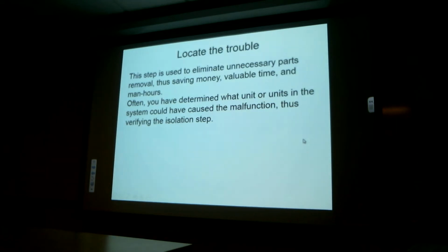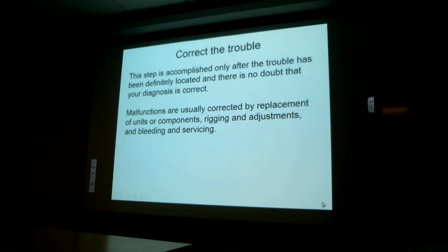The problem was that the vent opening at the fuel cap had been blocked by dirt. So I went out to the fuel tank, opened the tank up, and I heard this rushing sound of air entering the tank, and all of a sudden I realized what was wrong. So those two previous pumps really did nothing to solve the problem. All it was, was a little bit of collected dirt in the fuel tank cap and the vent opening that developed a vacuum on top of the fuel, and of course the pump can't overcome that, so the engine stopped. So I learned my lesson.